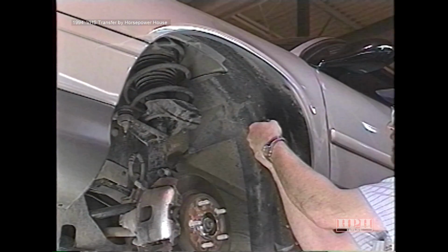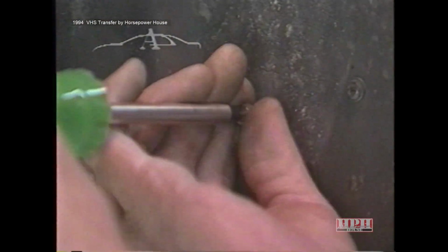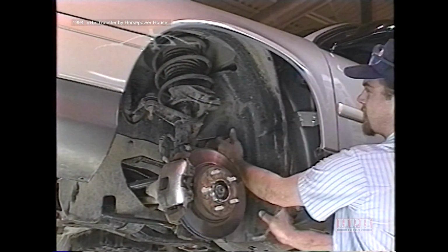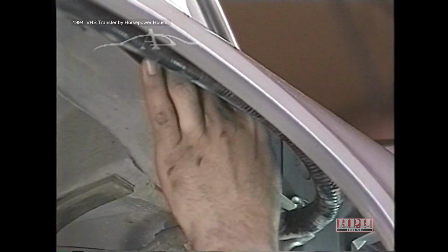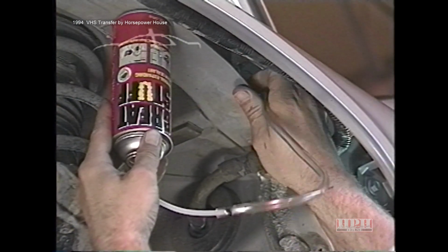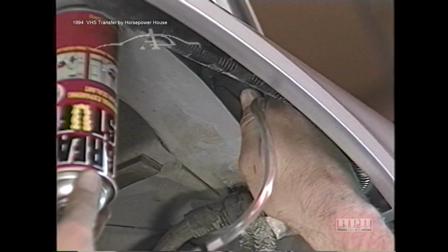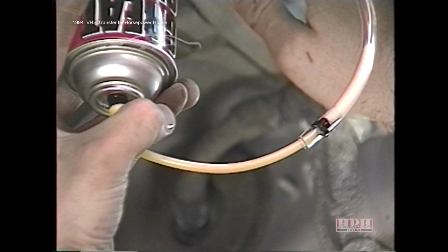To seal an A-pillar roaring wind noise, remove the 2 rearmost screws from the wheelhouse splash shield and pull the shield down to access the upper load beam. If there is a stuffer bag in the load beam, remove it through the access hole and discard it. Then attach a 12 to 18-inch plastic extension tube to a can of household aerosol foam sealer insulation and fill the load beam cavity with the foam sealer.